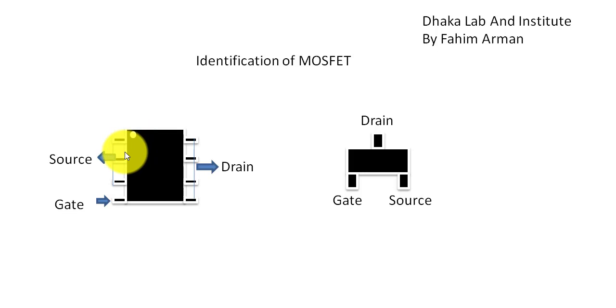These pins are called source, and after that there is 1 pin, that is gate. Okay, so you can say that this is pin number 1, 1, 2, 3, these pins are source, and pin number 4 is gate, and pins 5, 6, 7 and 8 are drain.